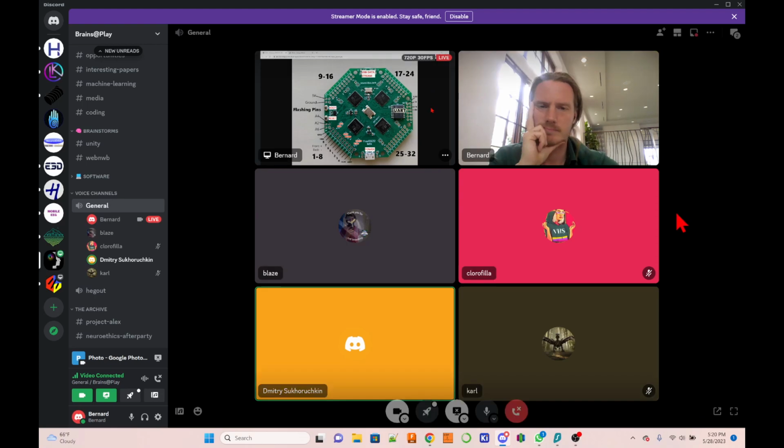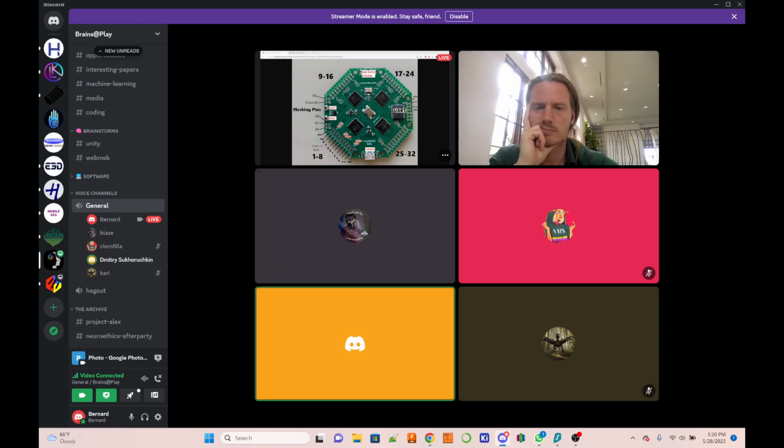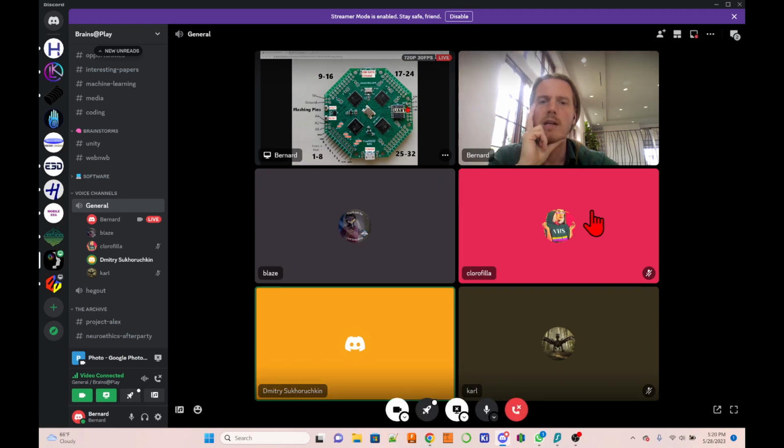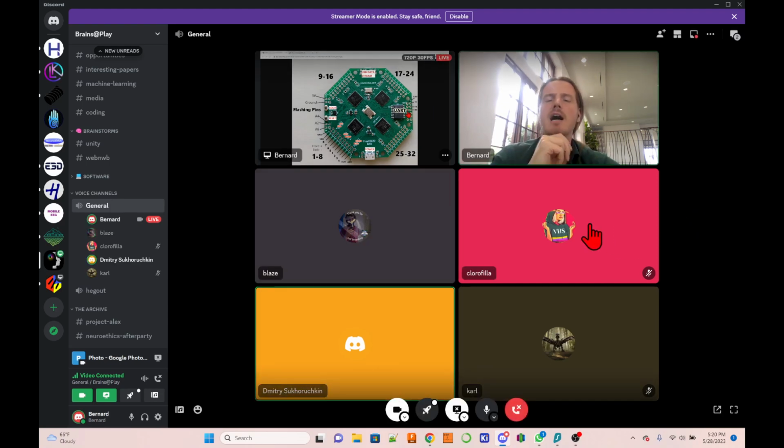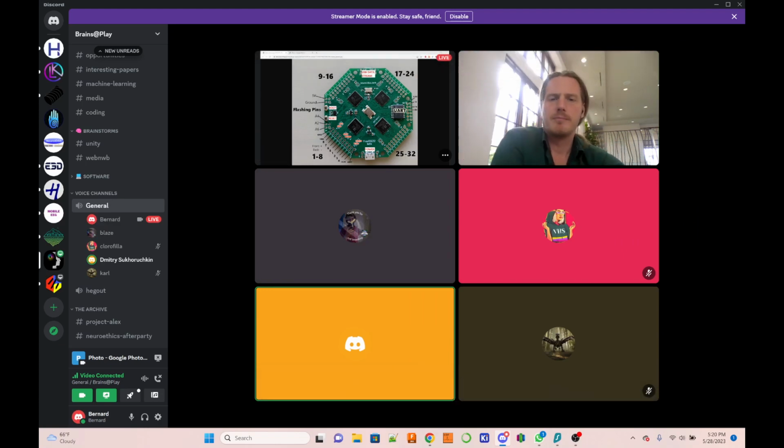If you connect a 3.3 volt microcontroller and provide 5 volts, you will destroy your microcontroller. So you need to provide the voltage your data needs: 3 for 3 volts, 5 for 5 volts.